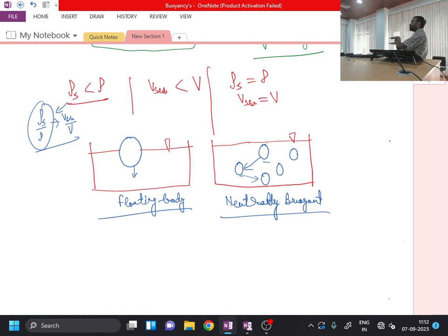So by tracking these particles, one can determine the velocity field of the flowing system. This is an important application of neutrally buoyant particles in areas such as particle tracking velocimetry and particle image velocimetry (PIV), which are advanced tools to experimentally determine the velocity distribution.